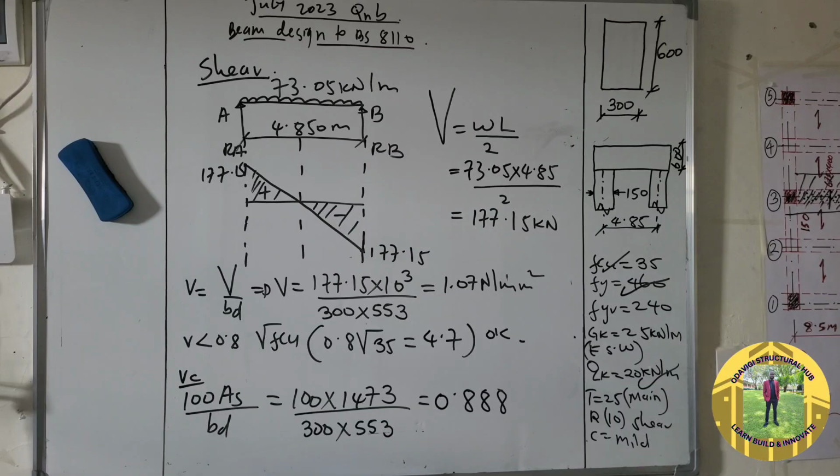class 25 of concrete. And then to get the Vc for class 25, you will take that 5 over 25 times the value obtained in this table, and you will get the Vc of class 25.